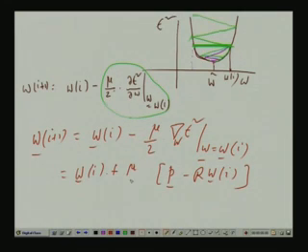Now, suppose you do not know what R is. Input is coming, you do not know its autocorrelation function, you do not know the P vector, and further, R and P are not static. From time to time they change, because the context changes, the scenario changes. The input statistics change, and the joint statistics between desired response and input, the P vector, change. So obviously, there is no fixed Wiener filter. For one set of R and P, you have one Wiener filter. After some time, if R and P change, you get another Wiener filter.